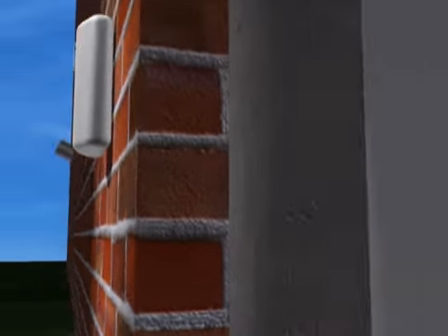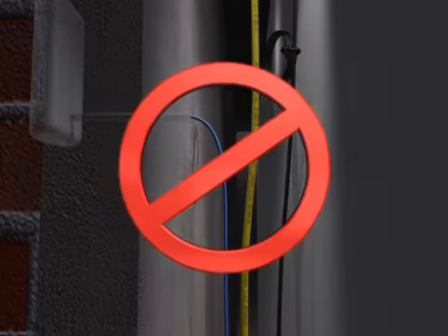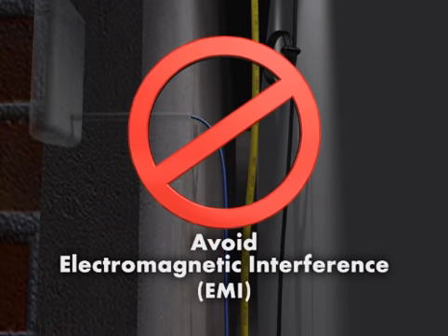If the sensor wires are located in an area with strong sources of electromagnetic interference, shielded cables should be used, and the shield wire should be connected to the manufacturer's designated terminal on the control, not to earth ground. Step 3. Install the boiler sensor.